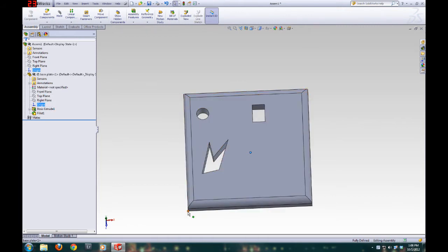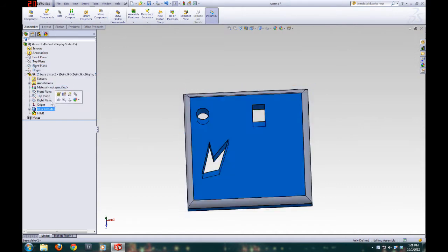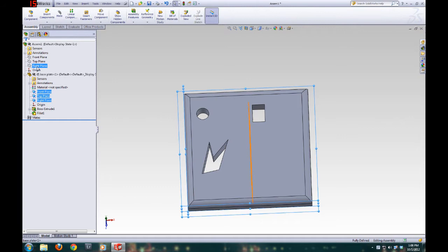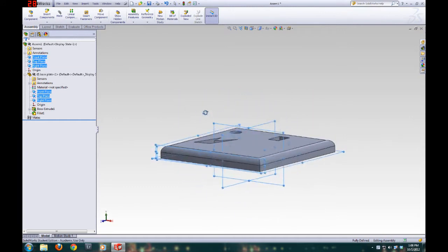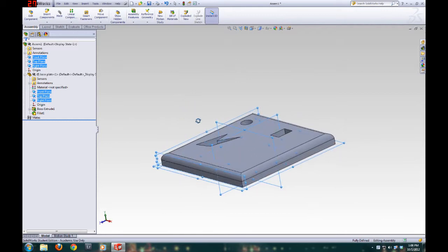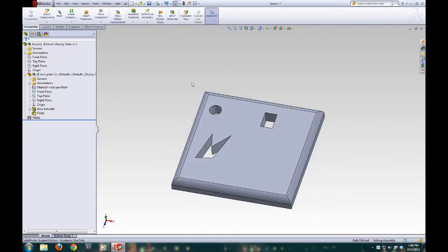These 2 dots correspond to the origin of the part. The origin of the assembly is all the way over here. There's no guarantee those are going to be geometrically related in a standard sense at all. The assembly origin and the assembly basic planes can be very, very different than the part basic planes. As you can see here, when we highlight the part planes and then the assembly planes, you have very, very different sets of default reference planes.